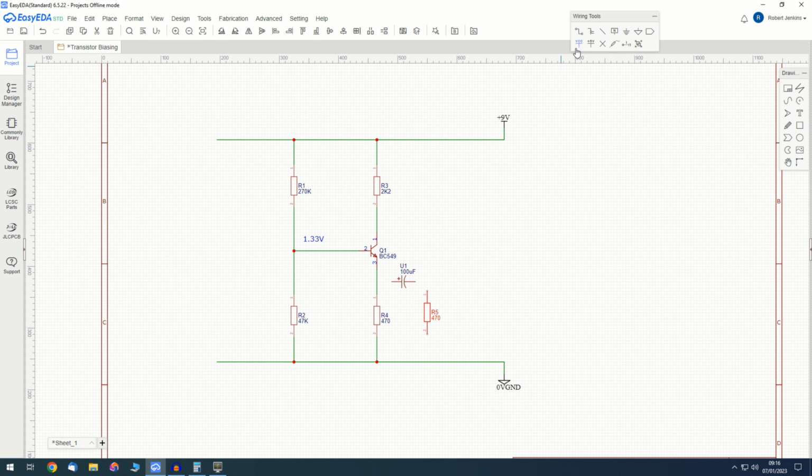Out of the way again. So another emitter resistor, but with a series capacitor of a high enough value that it's not going to affect the frequency response down to the lowest frequency you want the amplifier to work with.